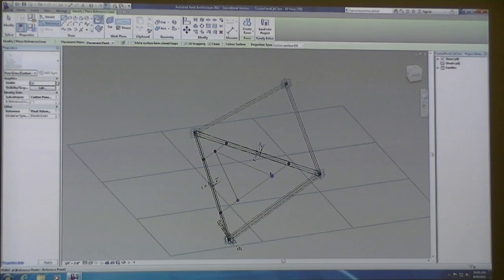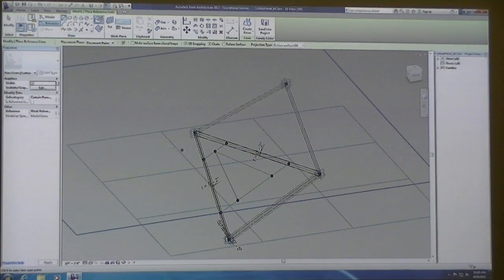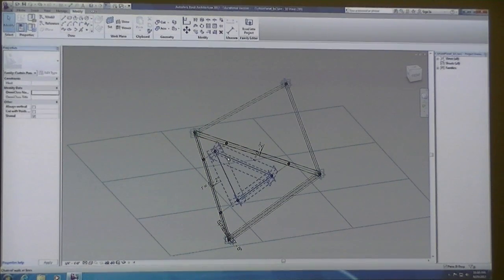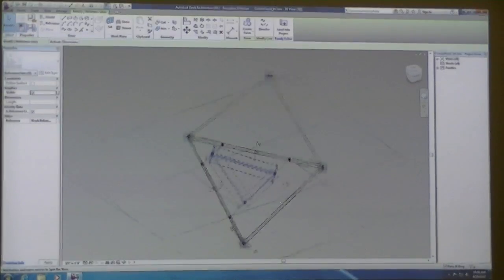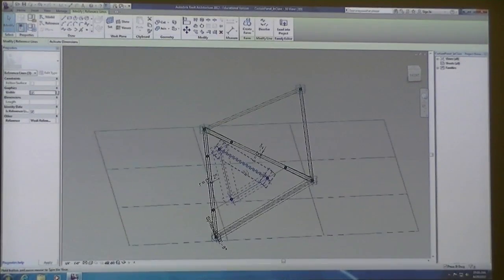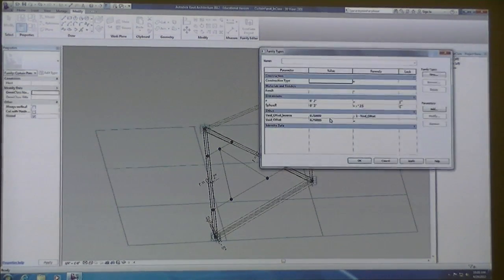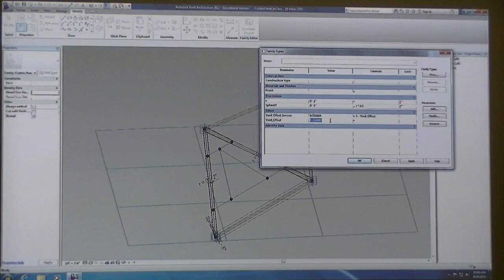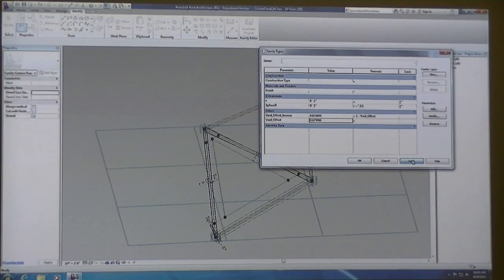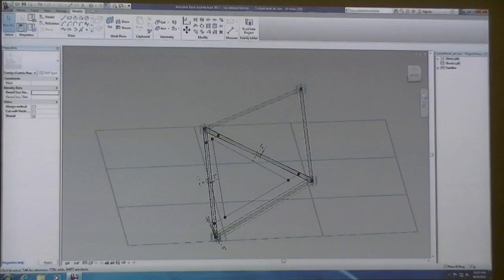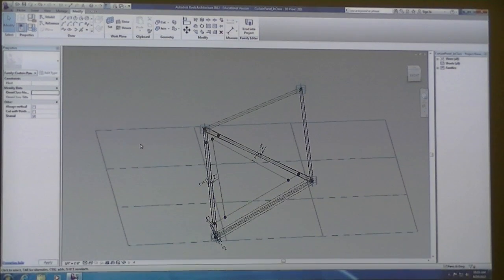And I want to close that shape and then hit escape. So I should be able to select a triangle that's here in the middle. We can test everything out, make sure you can change your void offset to some other value, and your triangle in the middle should also move and change.